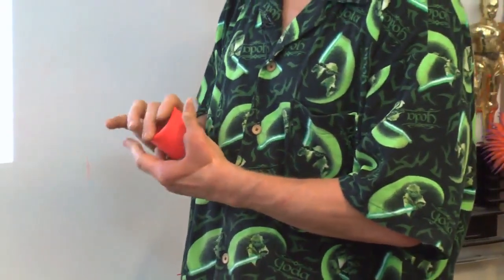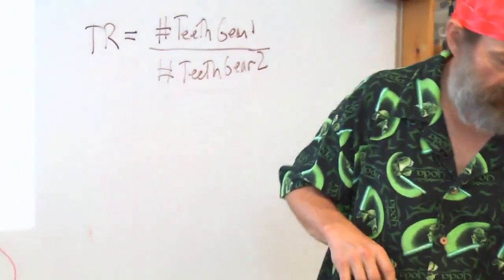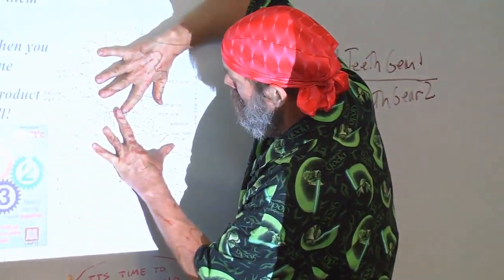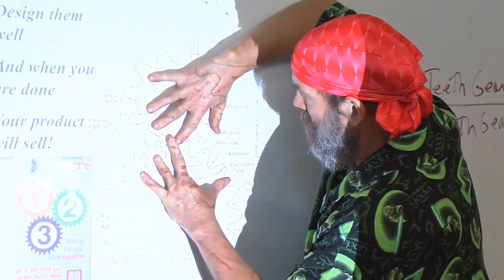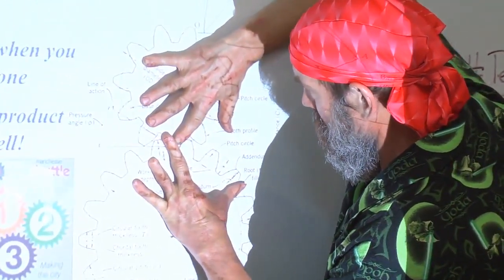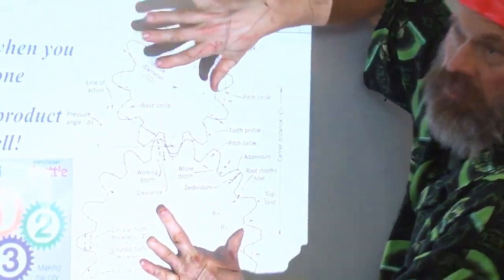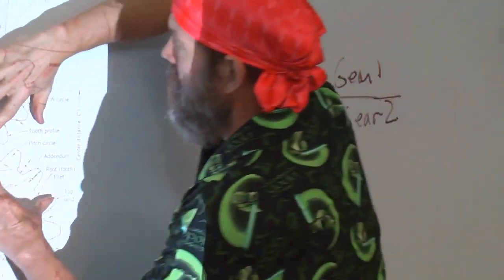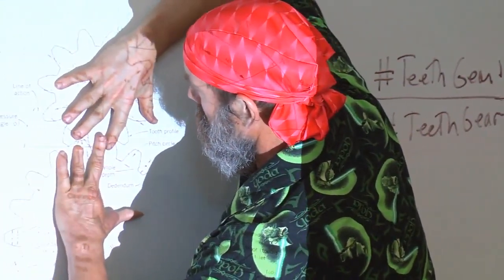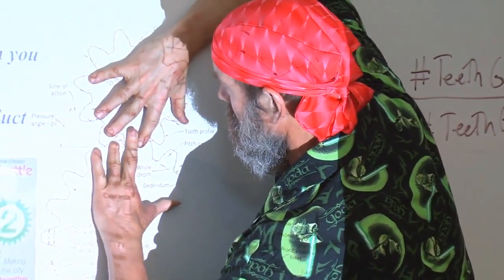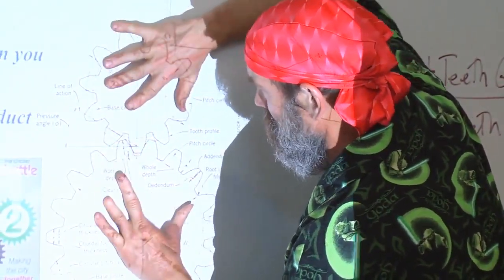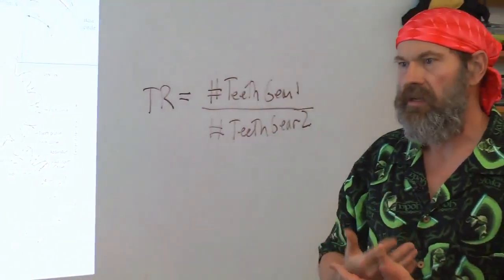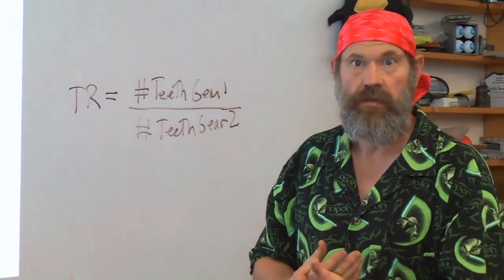This is called the gear tooth separation force. It's a function of the gears when they first engage at what's called the pressure angle. And when they start to push on each other, they want to push each other apart. So when the gears are rotating, the pressure angle is always there, but there's a point where the force is not trying to push them apart, to where the force is trying to push them apart, and it's a cyclic force. And any time you have a cyclic force happening, that's what can lead to noise. Okay?